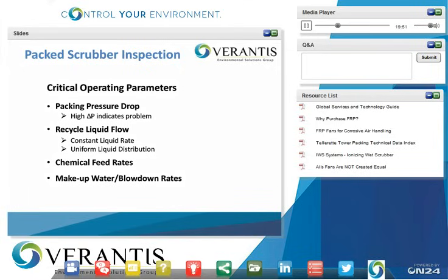And in the case of having too little chemical, obviously, then you don't have enough reactant to remove the contaminant gases, so that can reduce performance. In the case of too much chemical, that can also cause problems because then you can get other types of reactions occurring that can cause chemical scaling and fouling inside the system. So it's critical that the chemical feed rates and the concentrations in solutions be properly maintained with various analyzers such as pH control, ORP control, and conductivity control.